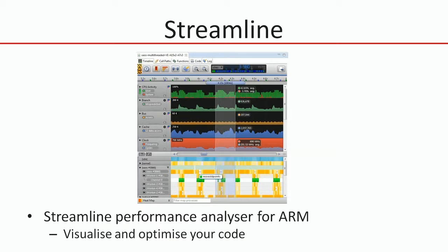Here at the top we have an activity trace that shows the loading on the processor, and at the bottom we have all of the thread activity, so we can relate the thread activity to the CPU activity. By clicking on the threads at the side here, we can show either the total aggregate view of all the threads or the individual thread activity, and we can select multiple threads to show their aggregate activity as well.